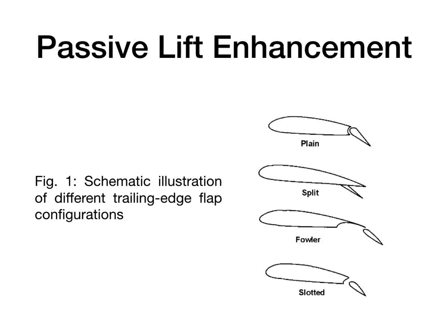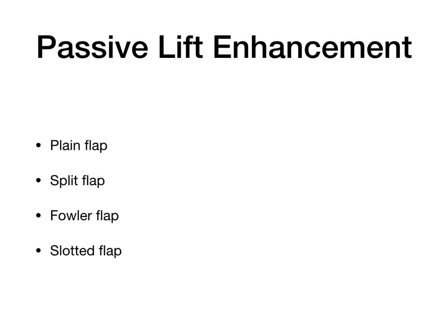Although trailing edge flaps increase lift at a given angle of attack, they do not increase the stall angle, that is alpha s, but actually cause it to decrease. This is the result of changes in the location of the stagnation line and local pressure gradient near the leading edge, which leads to leading edge flow separation. Sharper leading edges are more sensitive to this.